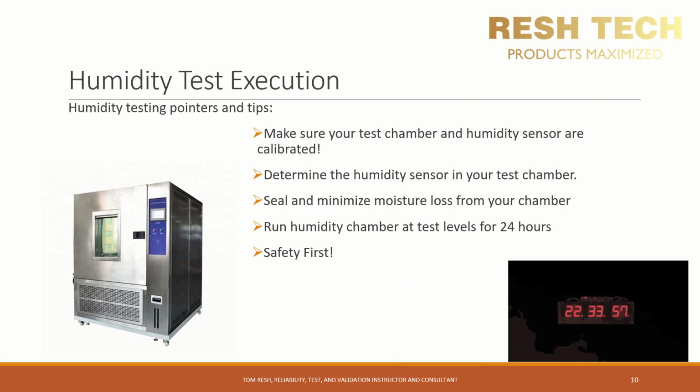Run your chamber for 24 hours as part of a pre-test checkout to ensure your temperature humidity chamber is working as expected before placing your test unit into the chamber. This is important to ensure you don't waste time when something goes awry with your chamber, and dependent on the industry, and if this is some kind of production acceptance test before shipping to customers, you may even have to scrap the test units and use new ones, wasting both time and money and making you look like a total idiot in front of your boss.